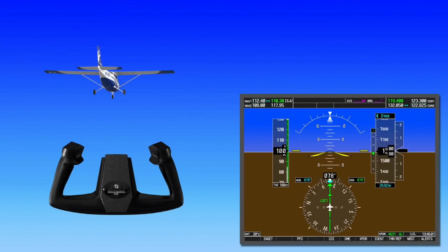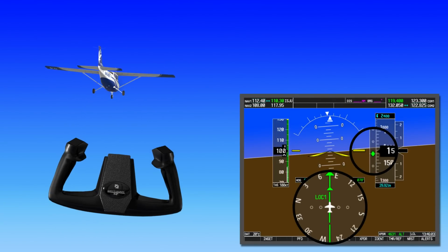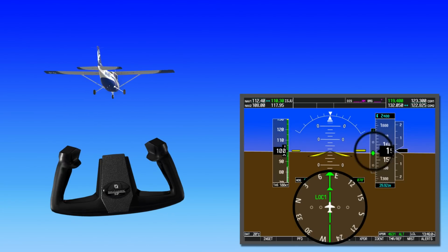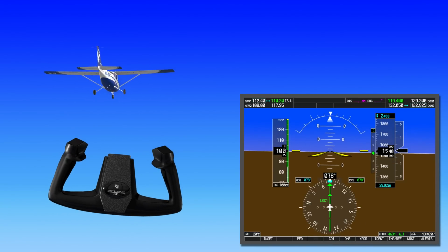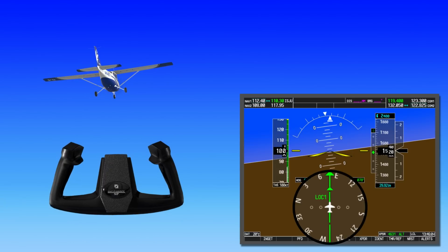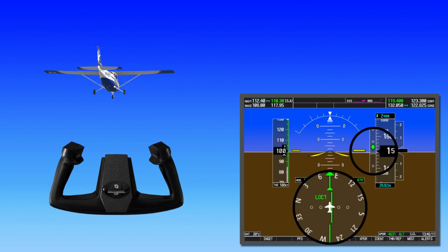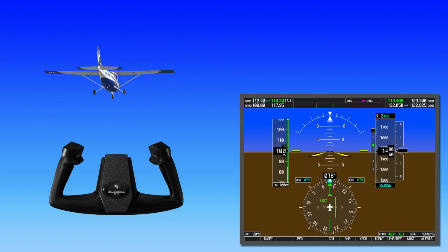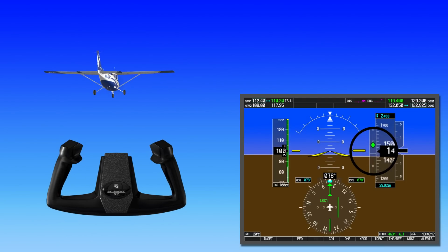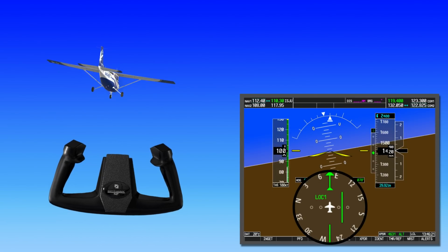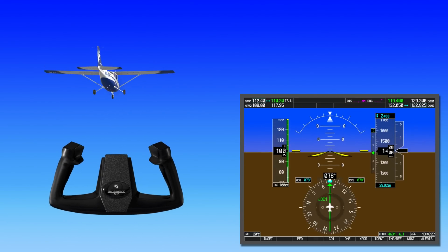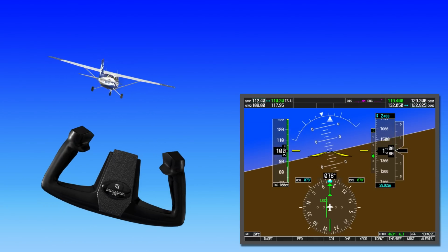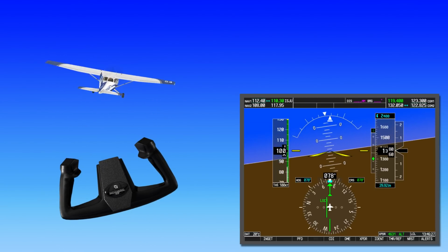From there, all you need to do is keep the green localizer CDI and glide slope diamond centered. This should remind you of flying an LPV approach. Remember, both the localizer and glideslope increase in sensitivity as you approach the runway, so focus on making small corrections. Apply corrections between 1/2 and 1 degree of pitch towards the diamond, and 5 to 10 degrees of heading towards the CDI needle. Applying too much correction is called chasing the needle, and will lead to erratic descent.